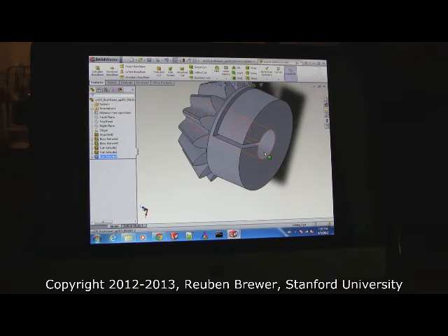You're good. So you said this gear was in the Yeah, you do it for me. Excellent. We're doing the rest of the extrude. Extrude one maybe, and then you walk me through it. Okay. I selected the wrong surface, so going back. Okay, now I have the circle. Okay, select sketch. Extrude cut. Offset from surface. Rotate the part.